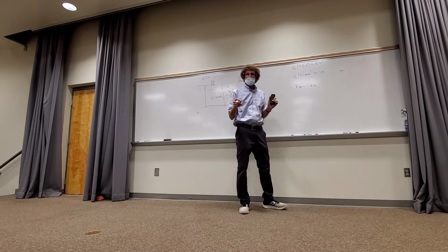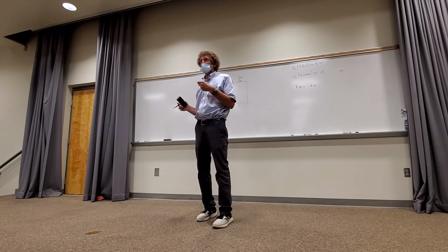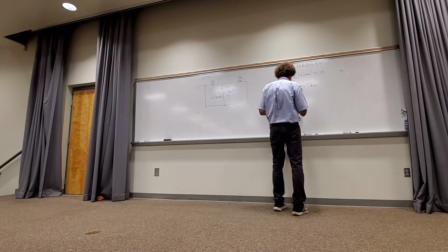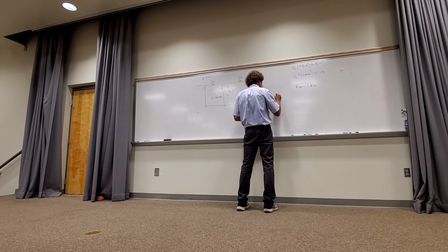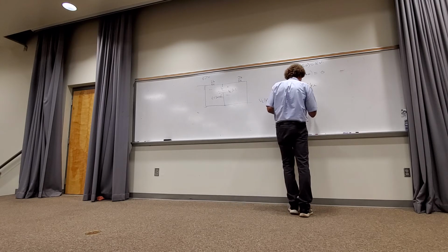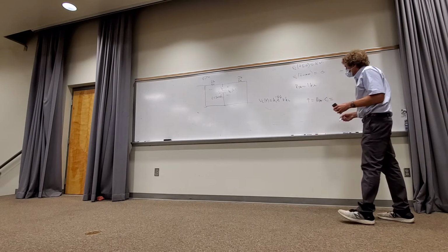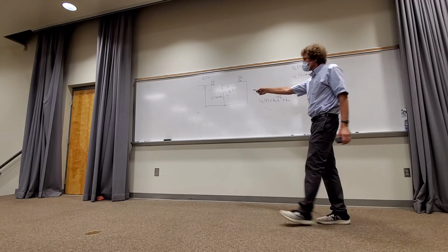Okay? Now, after that, we calculate the decay time constant called tau, right? And tau, let me put it, Vc as a function of t is really k1 e to the minus t over tau plus k2, where tau is equal to R Thevenin times C. Now we've got R Thevenin as 1k, that's 10 to the third, and then we have 200 microfarad.